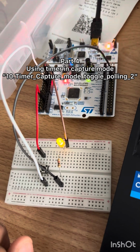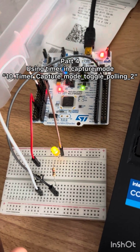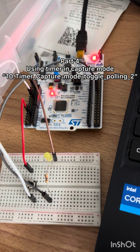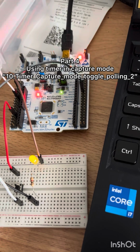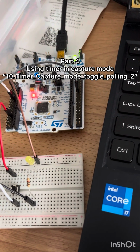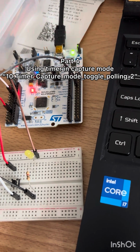In this code, there is no synchronization issue since the prescaler is set to 0, allowing the timer to run at maximum speed. And since ARR is set to maximum, there is no prerequisite value.